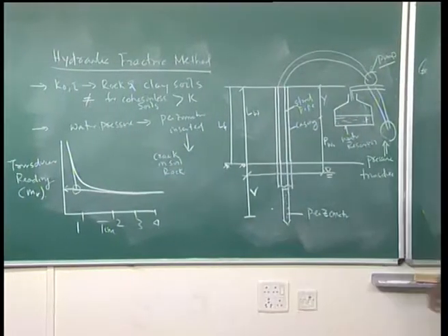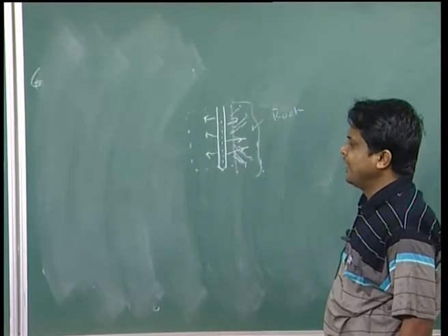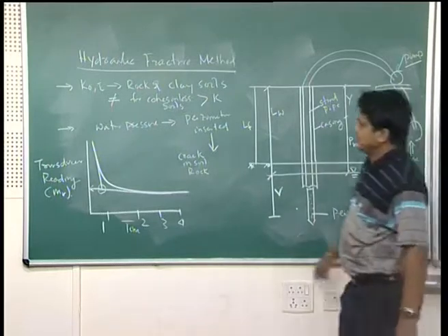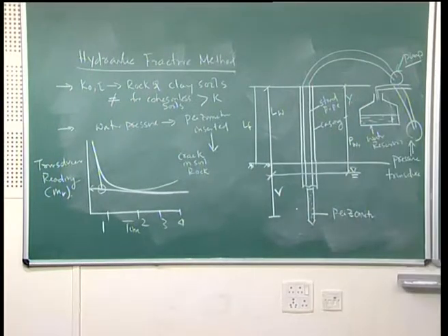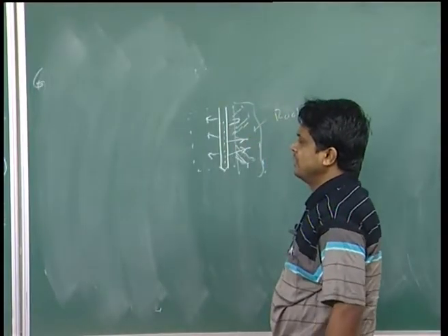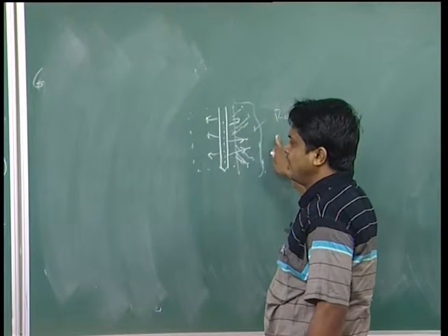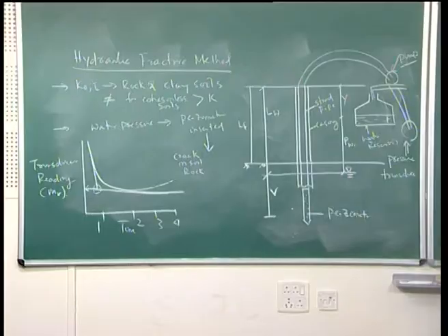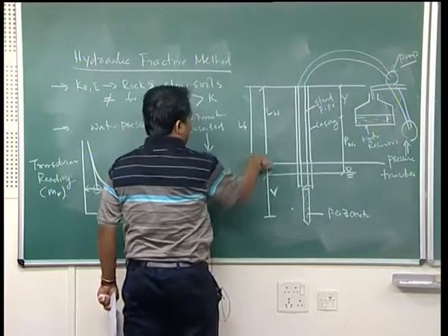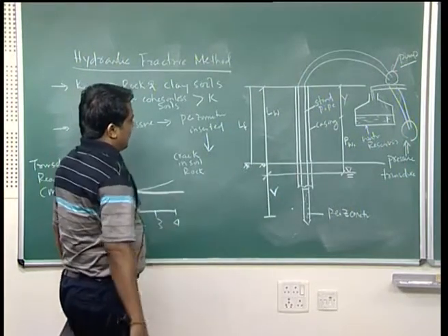it remains constant, no more further change in pressure transducer, or it may happen the pressure may fall. So, that point where it remains constant, that is your fracture point, or it relates to your sigma 3. So, you know what is this height, total height, where you are finding out your K0 or E maybe at this point.